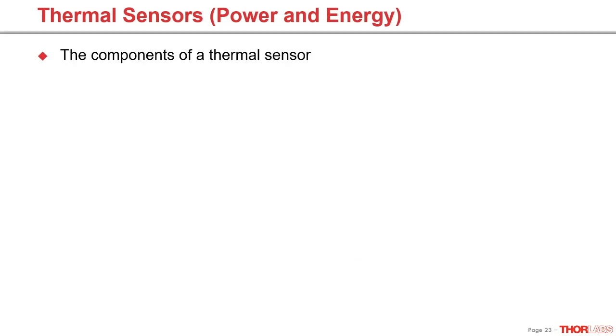To complete the thermal detectors for use as a measurement head, they need an absorption coating that can collect the incident heat. Black layers show the flattest absorption from UV to terahertz. When higher durability is needed, ceramic coatings are the best choice. For highest speed, metal coatings can be used as well.